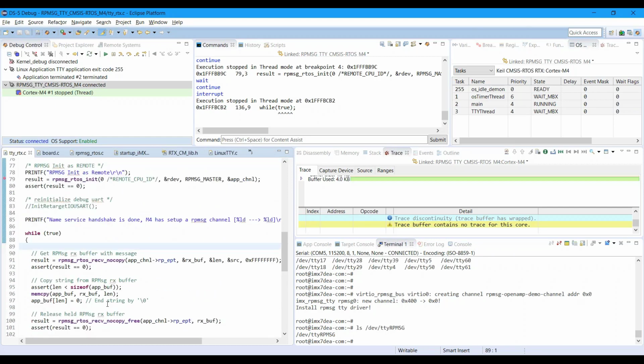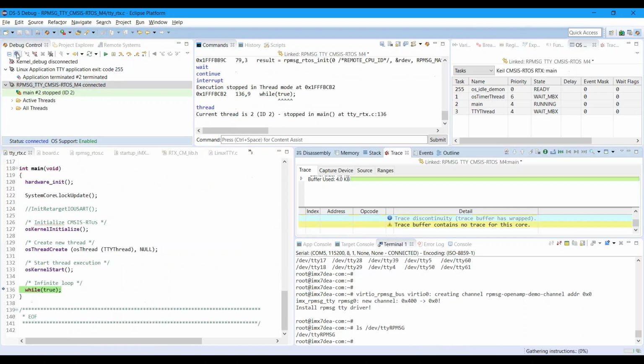And one very useful functionality that DS-MDK has is the RTOS awareness. As you can see here, the RTOS has different tasks actually running at the same time. So how can we find out, for each task, where it stopped? Where the last instruction was executed. One functionality we can enable is display threads.